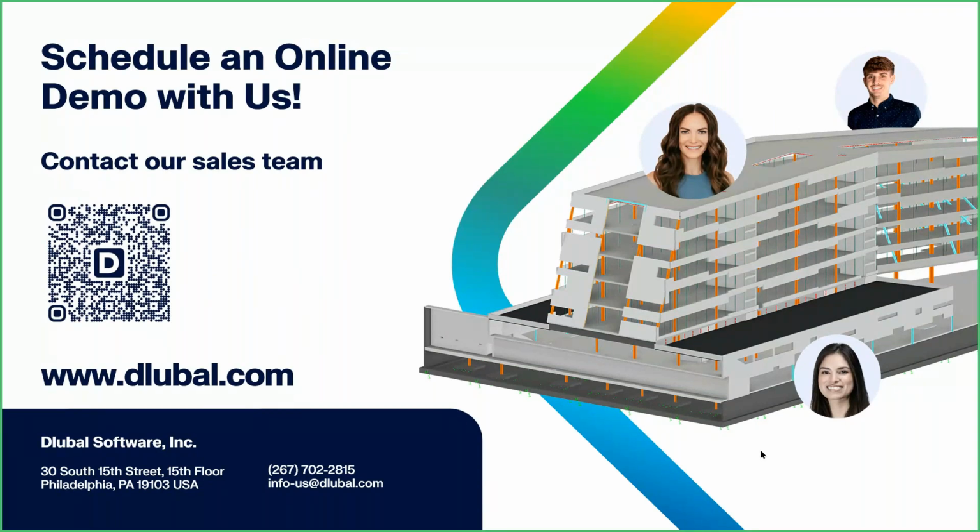So if there is a situation where possibly a drafter is on one computer and an engineer is on a different computer, we're not going to have these direct integration capabilities. As far as we know, there's no export of the analytical model from Revit, so therefore we would export the physical model as an IFC. So this is what Alex had showed with the import into RFEM. Unfortunately, the downside of IFC is, of course, our physical model. Things are not fully connected. So therefore, we showed how to connect those elements with those rigid links.